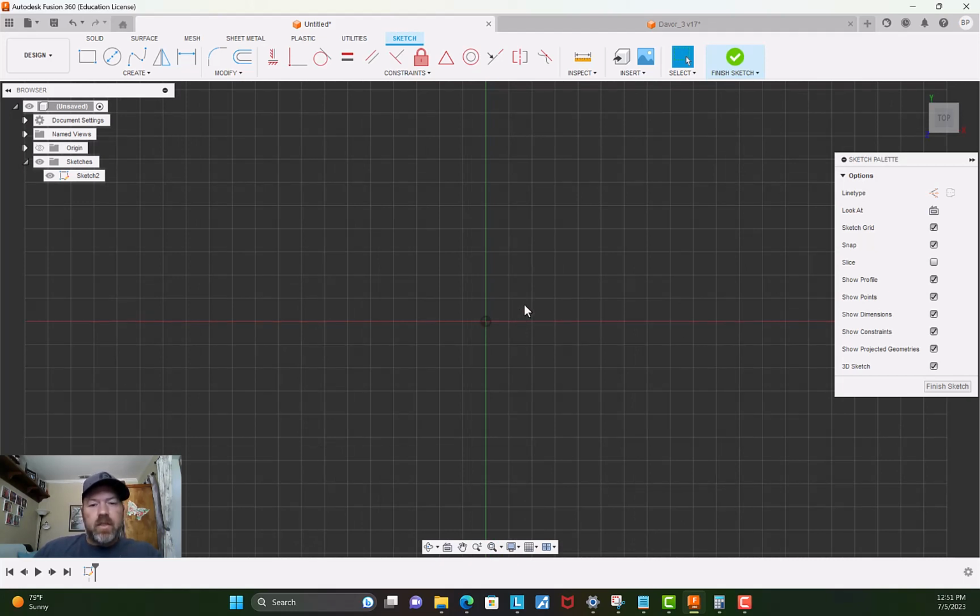There's a couple different ways you can go about creating your base cross section for your cue. If you know all of your dimensions for your cue, like what your butt diameter is, your A joint, and your joint, along with the widths of the rings that you want, you can just start at one end and enter your vertical links this way as you work along in the X direction.